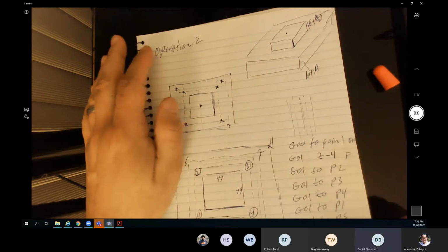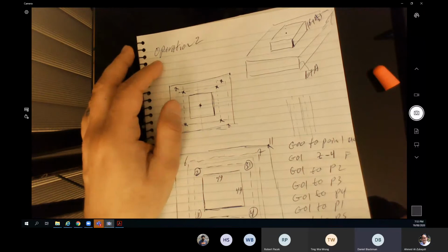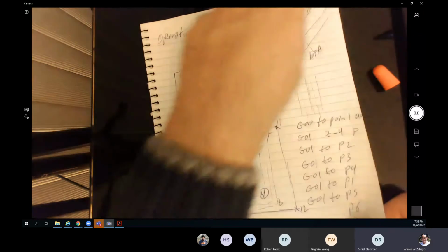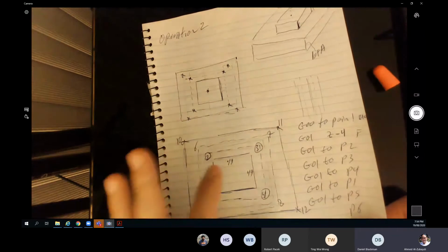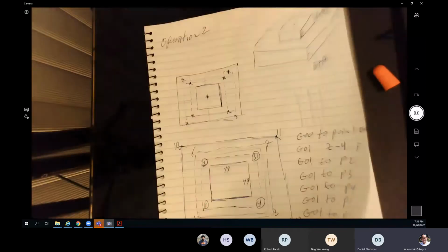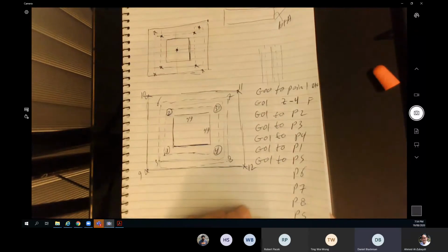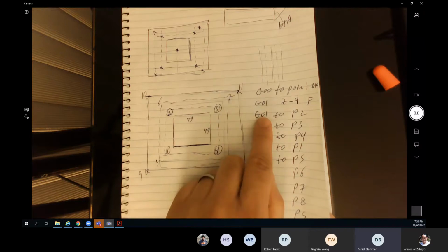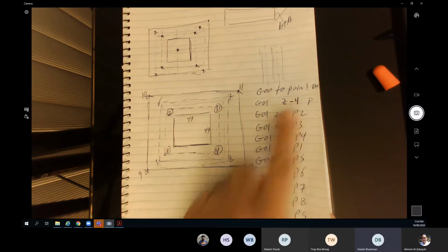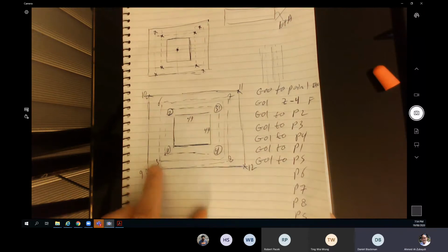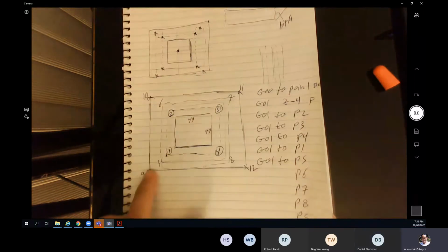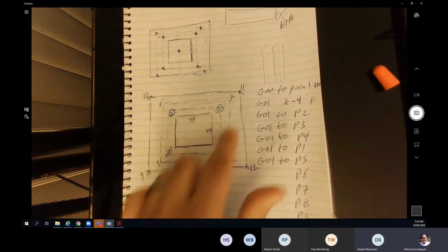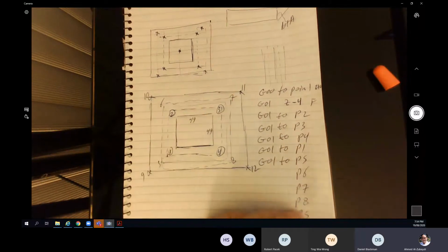I don't get why you're plunging down into the part at point number 1 instead of coming in from the side onto the part. Yeah, so we call it profile cutting around the square of dimension, whatever it is, 49 by 49 in my case. You can say it's 40 or 41 or whatever. It surprised me that the G01, if that's at point 1, is like boring straight into the part first and then moving sideways. I would have come in from the side on the part for the whole thing. You want to come from the outside to the inside? Yeah, it's up to you. Well, when you are going to find the location of the points, then it's up to you to start from 9, 10, 11, 12, 9. Then you go to 5, get it smaller until you go around this one.